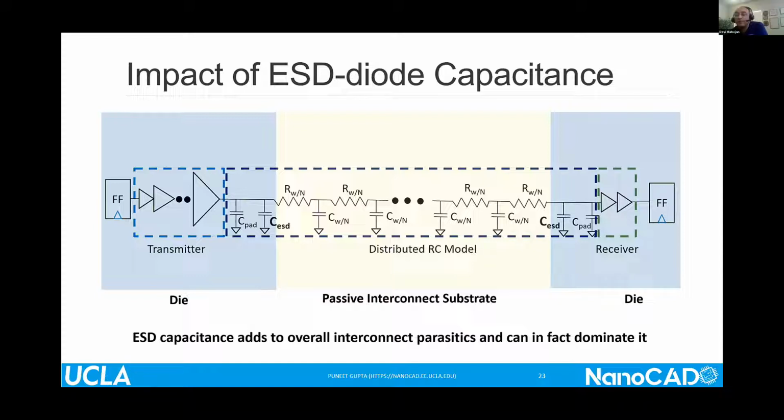I see. And if you break that up, ESD, is it more than the wiring? That depends on the metrics, right? So if I assume that it's just 100 micron die separation plus, let's say, 50-ish micron of buffer for dicing on each side, so that's about 200 microns of wire. And if you need 200 femtofarads of ESD protection, that will be completely dominated by ESD. Wire will play no role in it. But if you're doing 20 femtofarads of ESD, yes, the wire starts to matter.